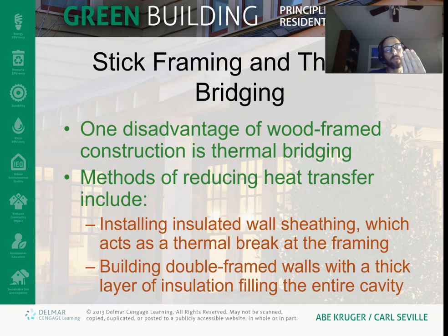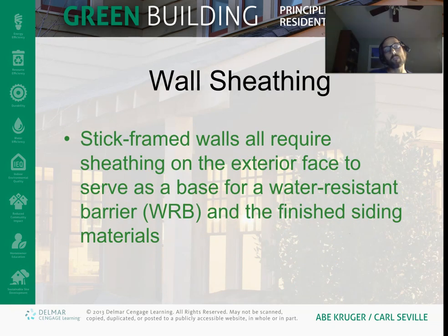So if you have a wood frame that's inside wall, outside wall, that's a thermal bridge. And metal framing is like 10 times more conductive, so it's a really strong thermal bridge. And so you want to have a thermal break. If at all possible, you want to have insulation completely continuous around the building. That's why sometimes in the more advanced and more energy efficient buildings, they'll wrap the whole exterior of the building in insulation to prevent thermal bridging.